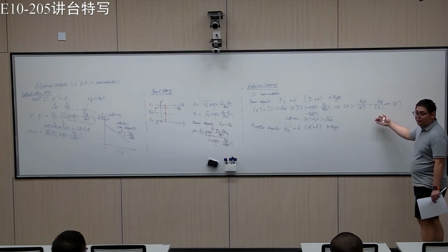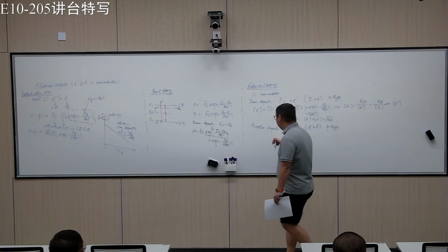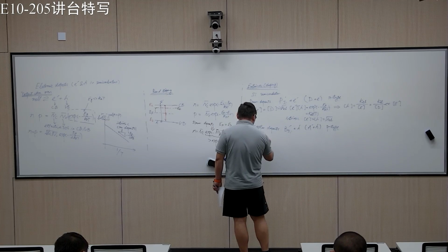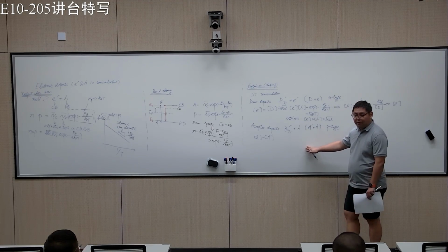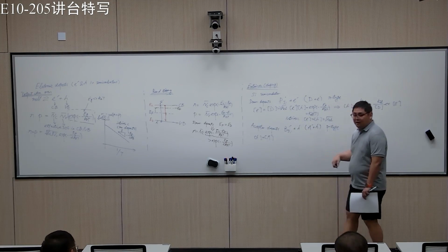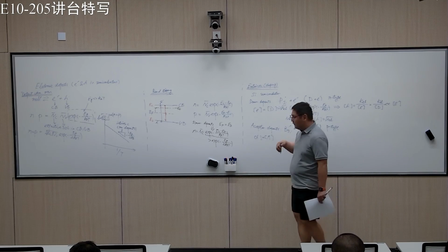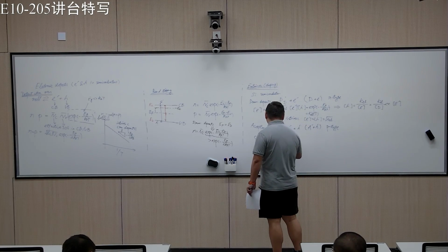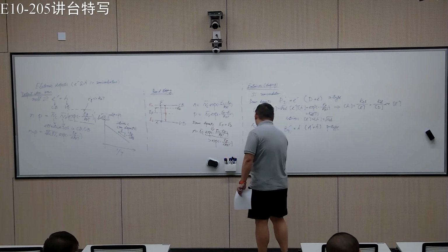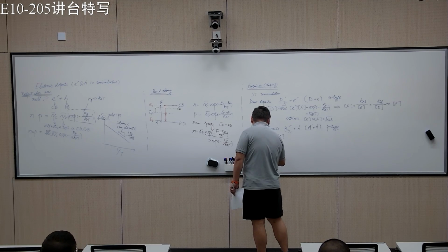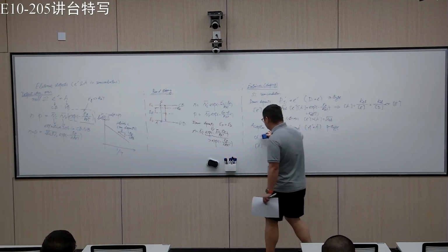Again, if we follow what we talked about using this kind of defect chemical reaction language, the number of holes will be fixed by the number of acceptors. Of course, we know that this is not the full electron neutrality condition, right? The real electron neutrality condition also has electrons. But because in this case the number of holes is much larger than the number of electrons, we can say this is roughly the same.